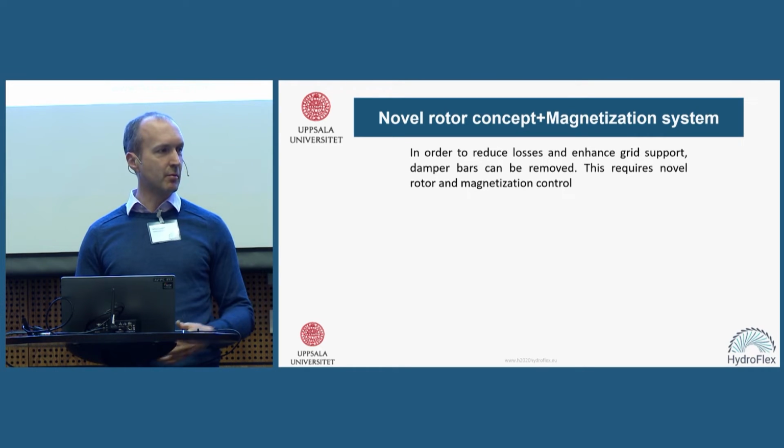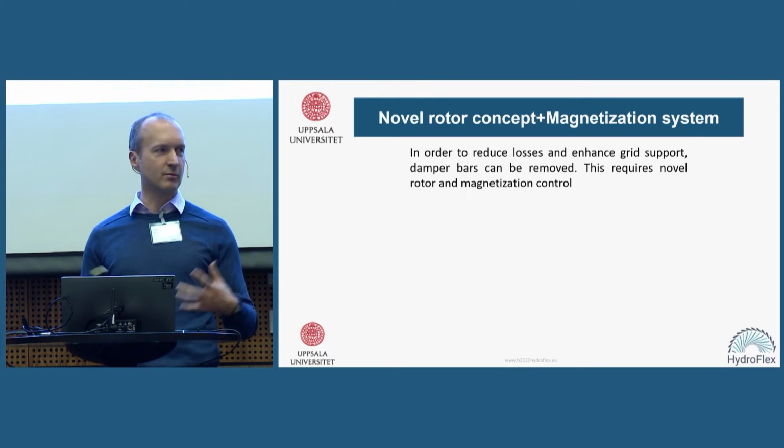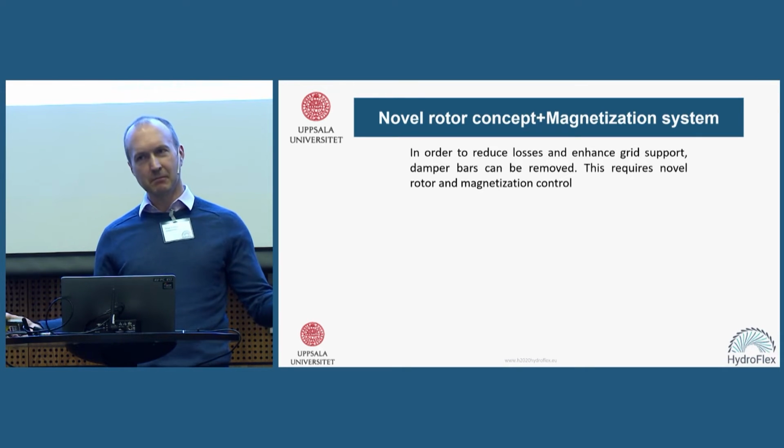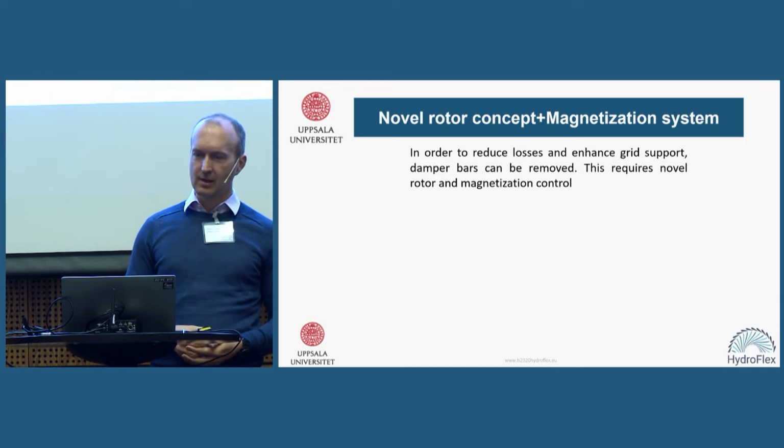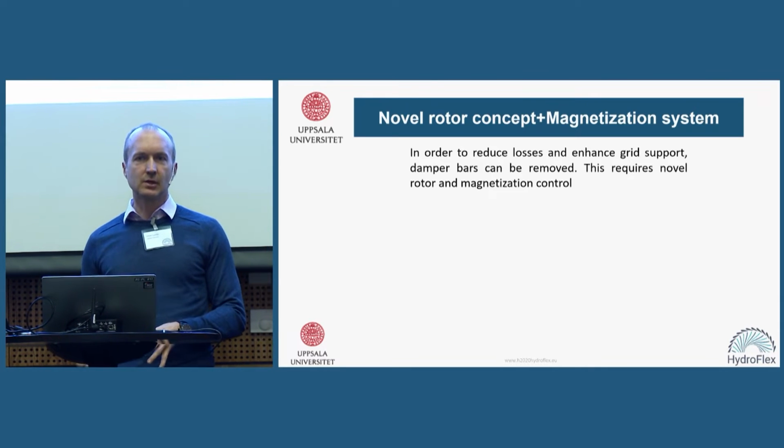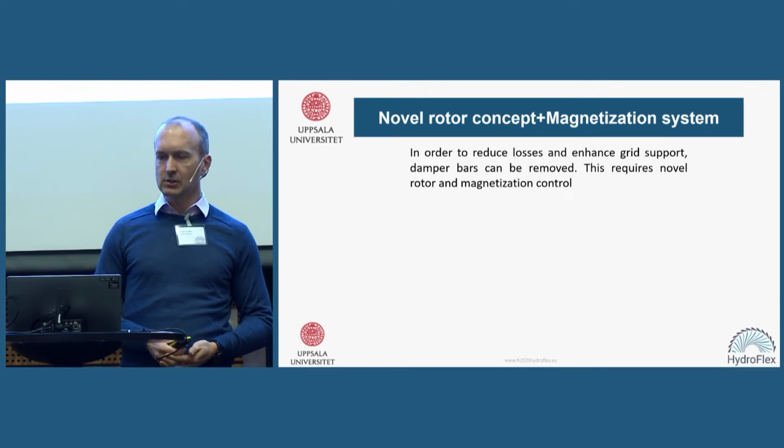We remove the damper bars, and that's sort of a contradiction. We want more damping, so therefore we remove the damper bars. Well, then we have to replace them with something else. So this requires us to do something novel on the magnetization system.